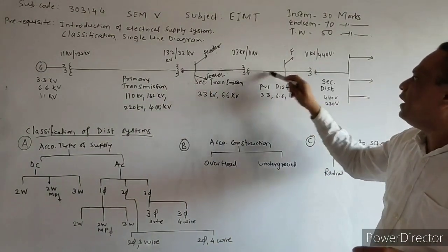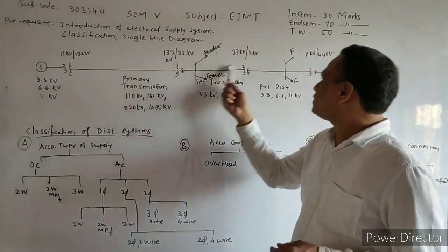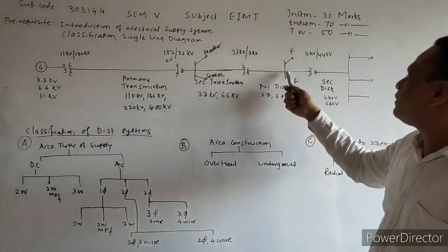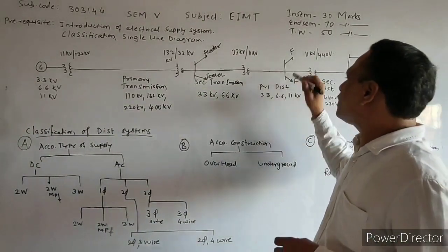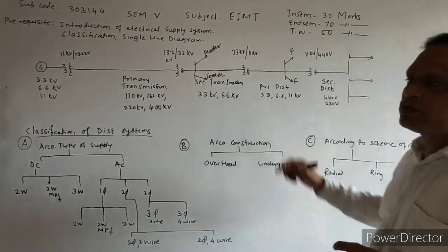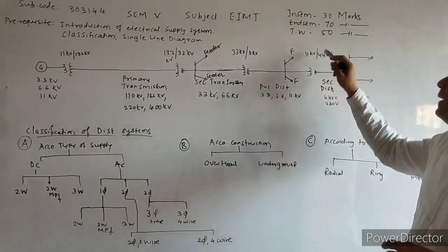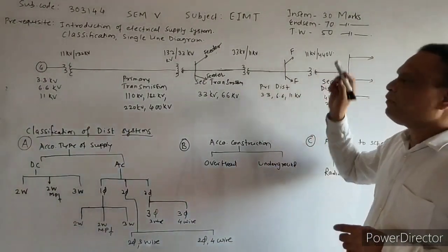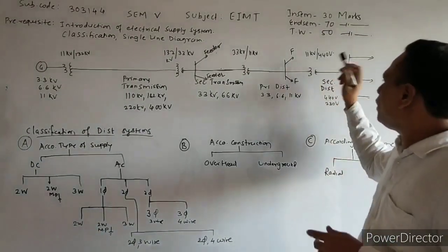Again up to this there is three-phase, three-wire system. So everywhere from this we can understand there is only a feeder system. So this will be called as a primary distribution. So this receiving station comes under the category what is called as a primary distribution, and after primary distribution there will be a transformer which will convert the 11 kV to 400 volt, 440 volt.